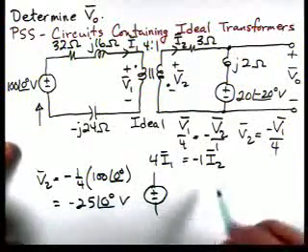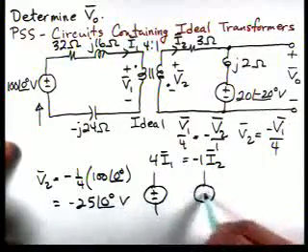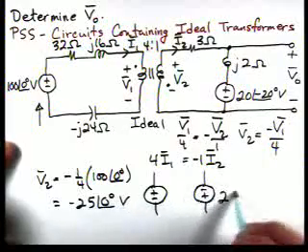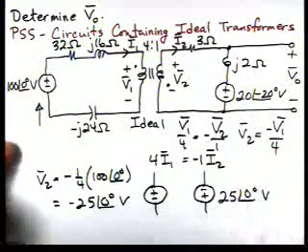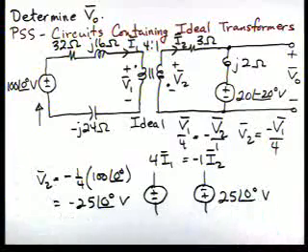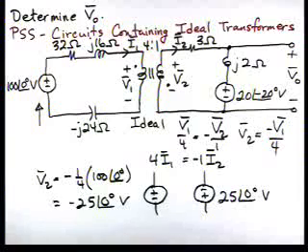Now, we could turn this over, change the polarity, and write it as 25 at an angle of 0 with that polarity. Now, the impedances just reflect by the turns ratio squared. So that's easy. It doesn't make any difference about the dot arrangement when we reflect the impedances through the transformer. So we're going to divide them by 16.